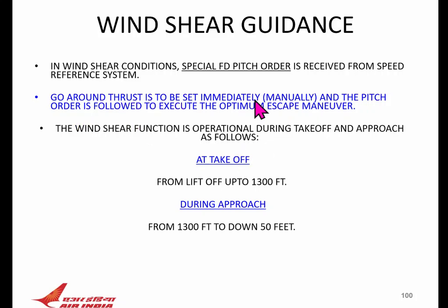Go around thrust to be set immediately, manually, by the pilot. Which order is to be followed to execute the optimum escape maneuvering guidance? It means there is no other option than to fly away. Just apply the TOGA and run. Okay.